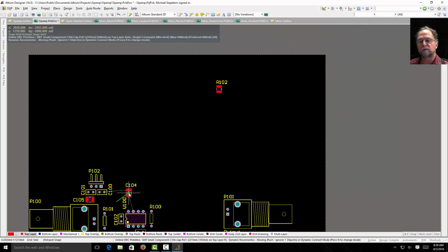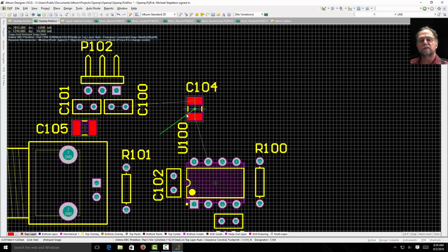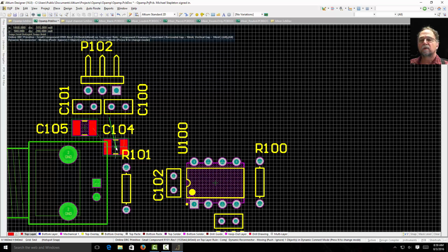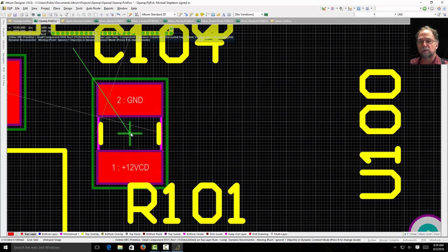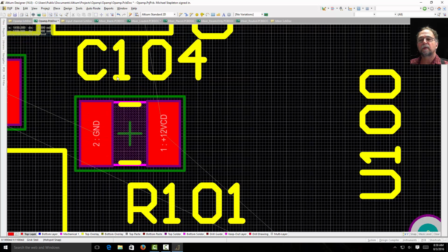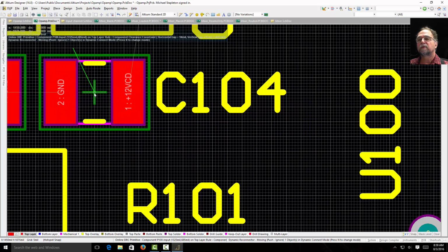Here's another one. I can zoom in a little, it's easier to see. Now, I don't want to put it this way. If I do, look at my net lines, they're trying to cross. So I'll rotate it, move my text, place my part.